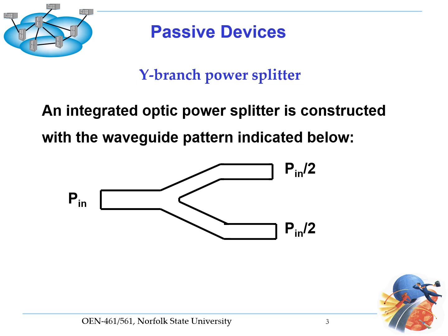And here is an example of a Y branch splitter or coupler. So we have incoming light that is split from one waveguide between two waveguides, and the light is split 50-50. This is essentially a 3 dB coupler.